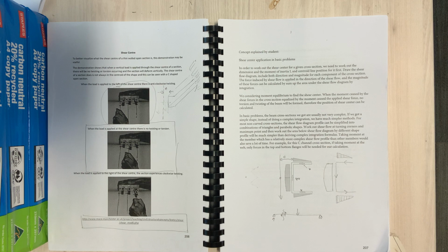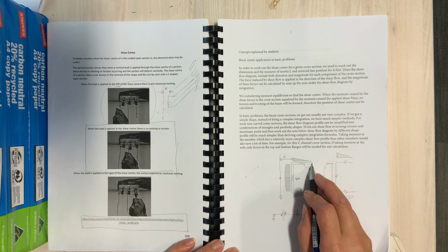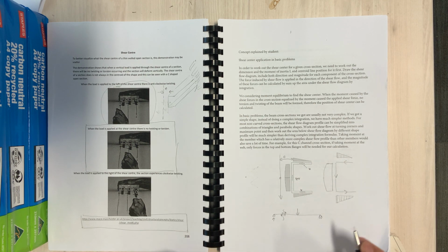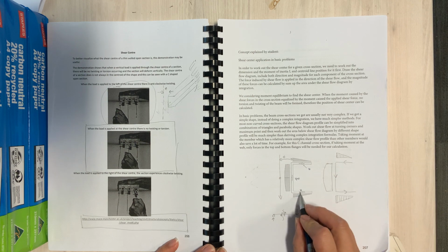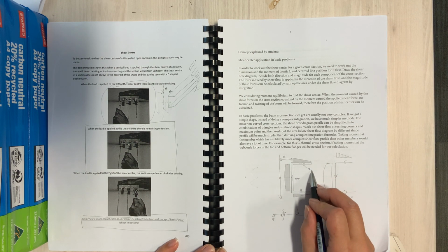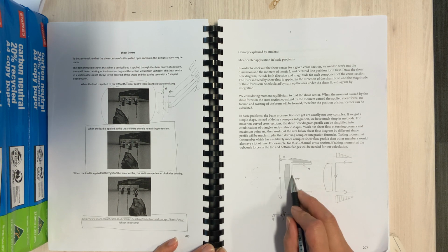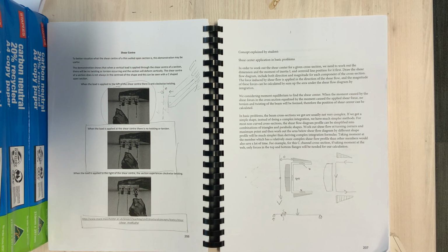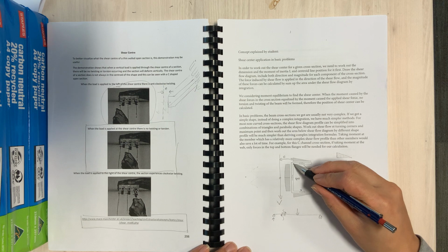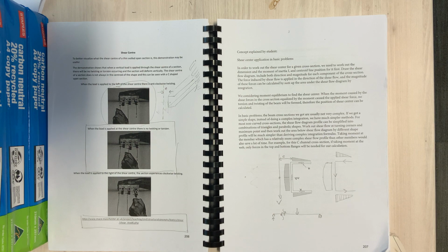Okay. And of course, one of the big assumptions with thin wall, which I just like to call working things around the center line, is that this flange here, this flange here and this flange here don't carry any vertical shear. So if you integrate under here, that would give you that V_e would be equal to the applied force V. So one of the thin wall assumptions is that your horizontal members, the flanges, are not taking any vertical stresses.